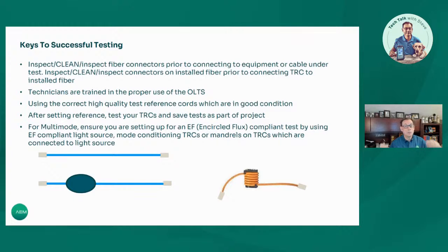I've had people actually try to run a test, and it turned out they were using a single mode reference cable with a multi-mode, or a multi-mode reference cable with a single mode test. It can happen. So make sure you've got the correct cords. Again, after setting your reference, you want to measure your test reference cords, and you can save that as part of your project. That's good practice.